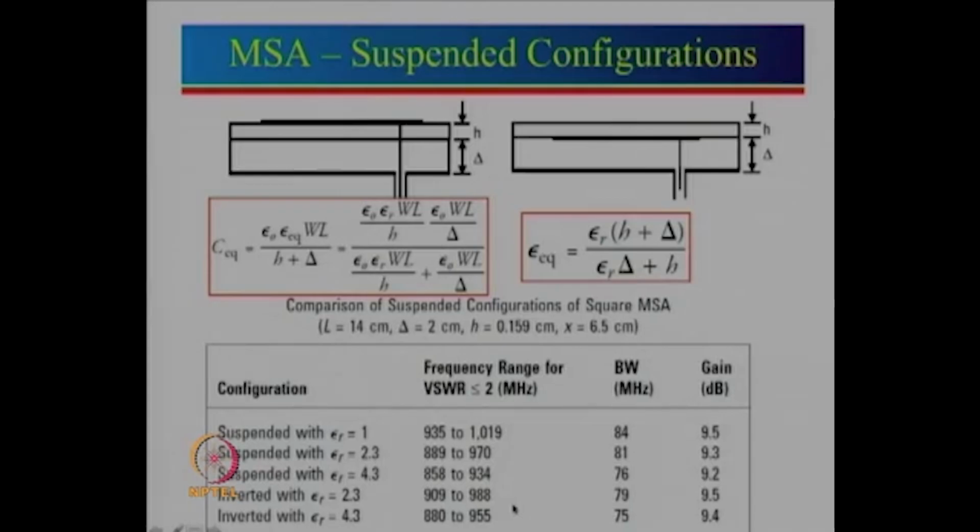Generally for commercial applications, one uses FR4 substrate, and commercial applications can be, let us say, you want to design a GPS antenna, or you want to use it for cellular communication, cell tower radiation and all that. But for defense and satellite communication, generally performance is much more important, and also thermal variation and other things are reported.